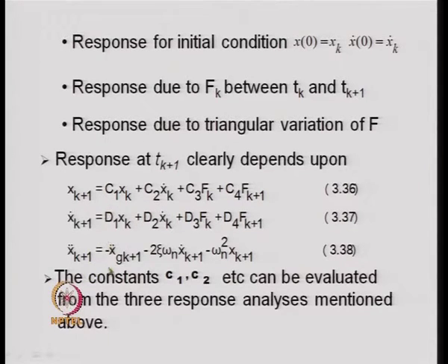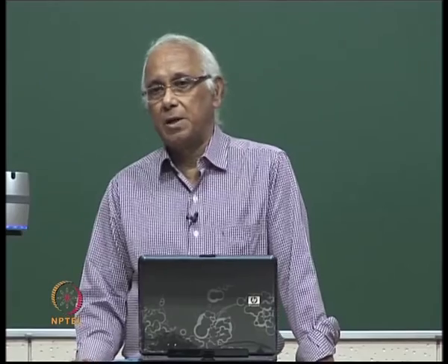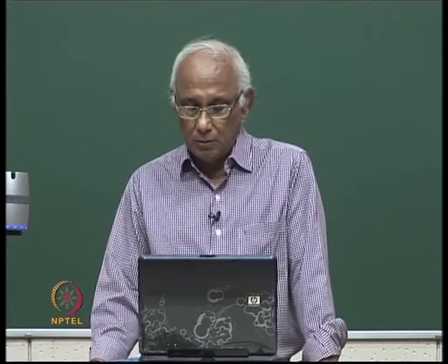So, using these three equations, one can get at any time step k plus 1 all three quantities, that is the displacement, velocity and acceleration, in terms of the displacement and velocity at the previous time step k, and the forces acting at k and k plus 1, which are known.